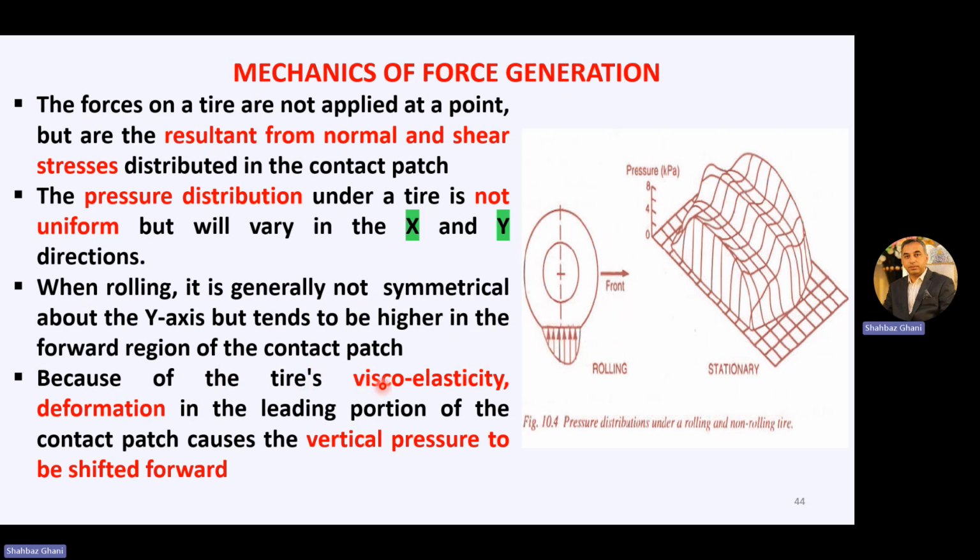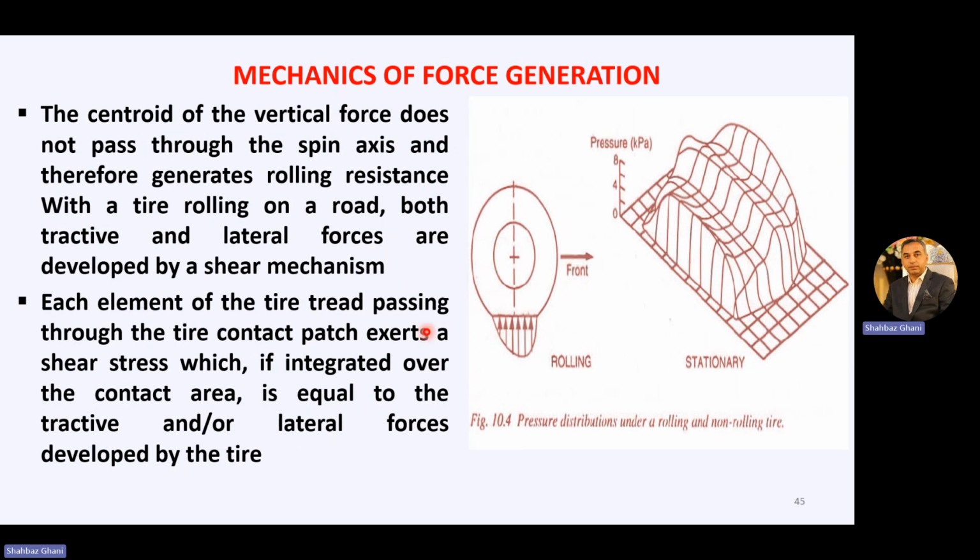Because of the tire's viscoelasticity, deformation in the leading portion of the contact patch causes the vertical pressure to be shifted forward. So this is how the mechanics of forces is generated in the tire while rolling.